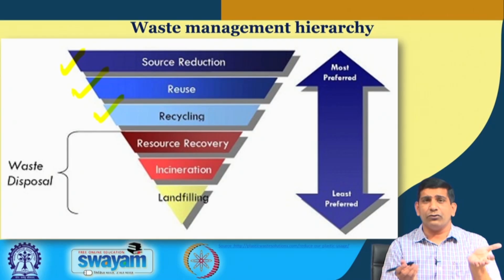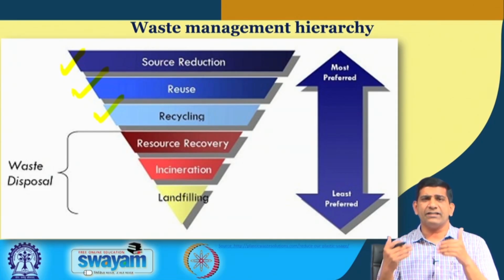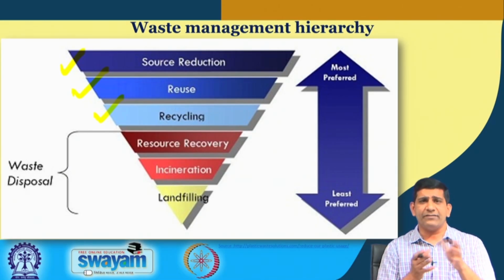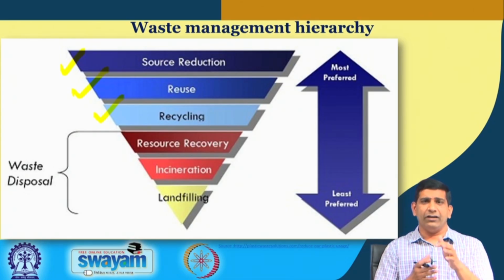Some cannot be recycled. PET and HDPE are pretty good in recycling, but there are certain types of plastic which are not that easy to recycle. And when you go for recycling, they may actually end up doing more harm to the environment, because of the type of energy and water requirement to make it recyclable. If you do a life cycle assessment, you may see that actually it is not really doing much environmental good. In fact, the environmental footprint of the recycling process is much higher than making the virgin plastic of that particular type.